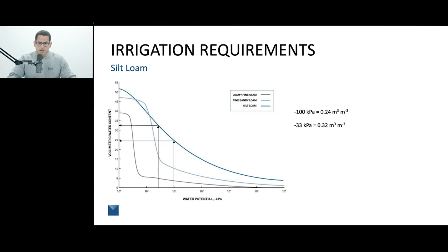This then gives us the information with the water content. Let's say we have an irrigation zone of 15 centimeters or 5.9 inches. If we want to get to our target upper threshold where we're not going to overwater and potentially lose water due to drainage or keep our soil too saturated, this means we have irrigation requirements to hit that threshold based on pretty simple math that you can see here. In order to hit that threshold, we need to apply 1.2 centimeters of irrigation, or about 0.47 inches. So this gives us more information for this silt loam soil.